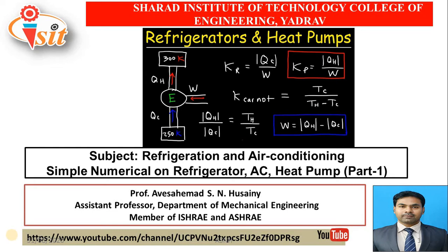The most important thing in the case of a refrigerator or heat pump or air conditioner is that performance is calculated by the COP, the coefficient of performance. For a refrigerator, the coefficient of performance is equal to the refrigerating effect upon the work input to the device.